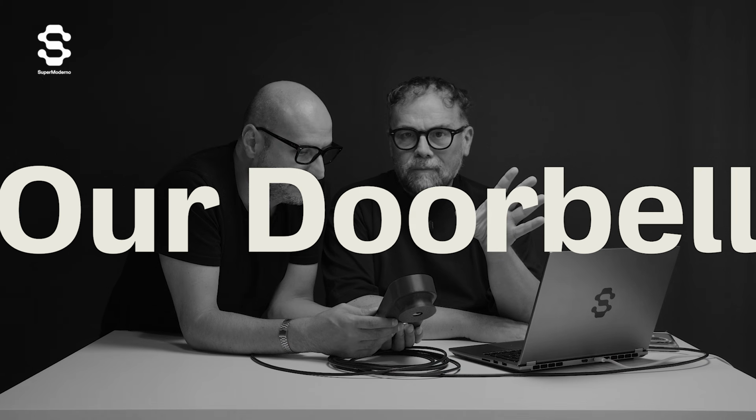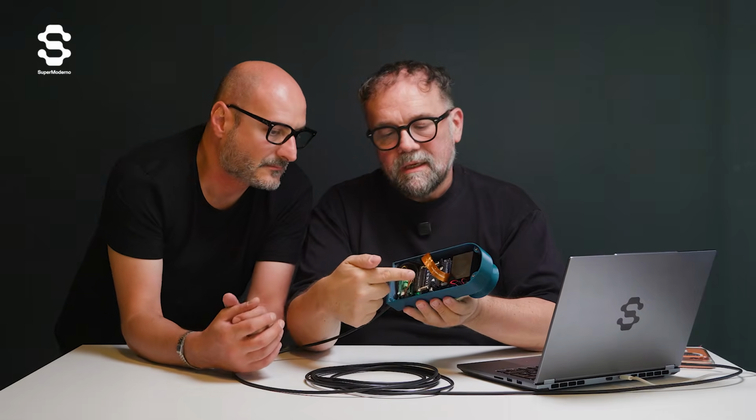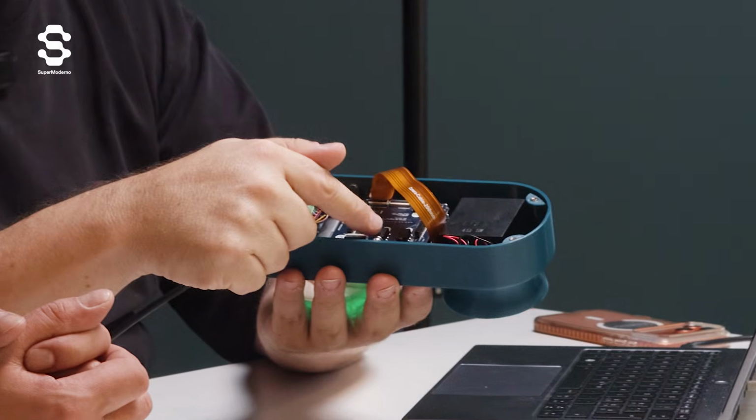So we got very far. So the architecture, just to recap on the nerdy details: basically I have an Arduino UNO Q, which is mounting this thing called the media carrier, which allows you to connect 2 cameras and a DSI display. At the moment we're not using the display, and you have 3 audio connections, 1 for a microphone, 1 for an earphone, and 1 for a headphone.